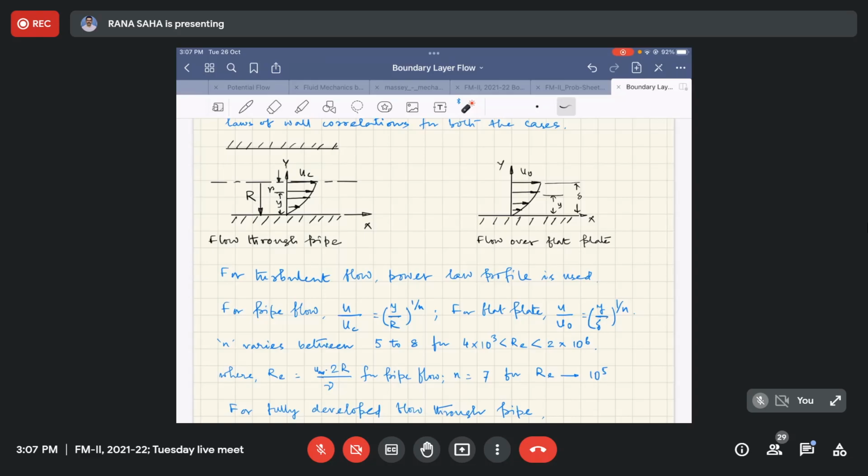One of them was the length. For the same diameter pipe, different lengths were chosen, and the pressure drop across that length was measured, with the same flow used through the pipe. So your V, the average velocity, remains the same if your cross section is the same.